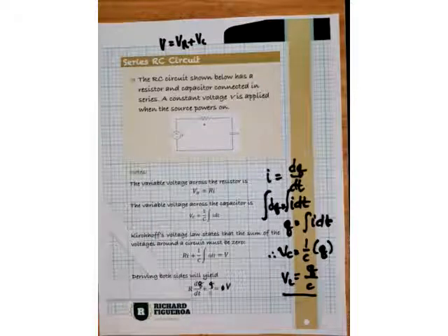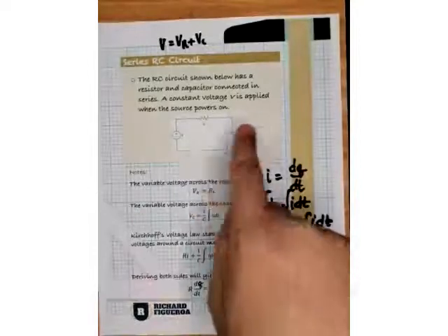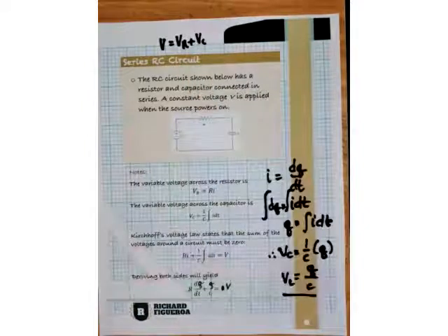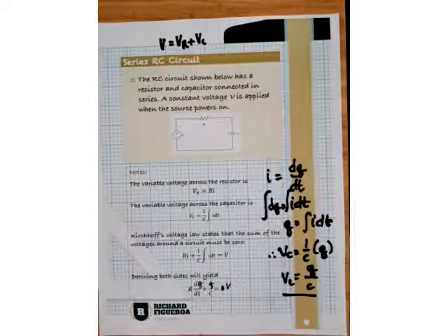So these are capacitors in series with the resistor. And again, they are connected to a voltage source, V. Same lang naman din. So if we will perform KVL across the combination, that means the total voltage will be equal to the voltage across the resistor plus the voltage across the capacitor.